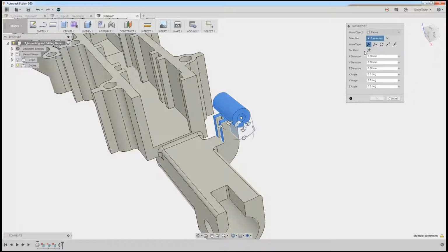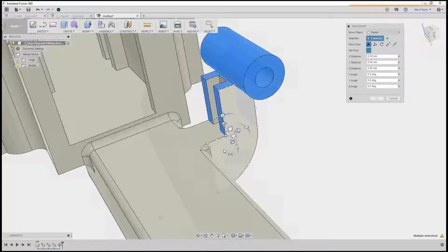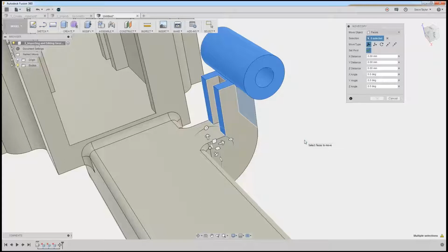So up here, if I go into pivot point, I can actually now select where I want to move this from. You'll notice if I hover over a side, then I've got different icons that come up. I've got a triangle, which is notifying me of the midpoint of a line. I've got a circle, which is the end point. I've got a square, which is the center of the shape. I'm just going to pick that point there. Now, one thing I need to do once I've set a new pivot point is to come back up and say done. So that's my new pivot point.